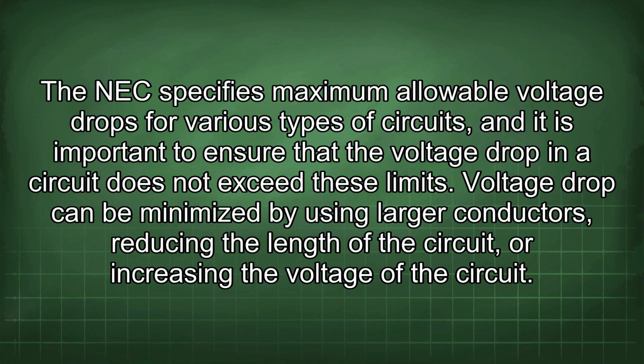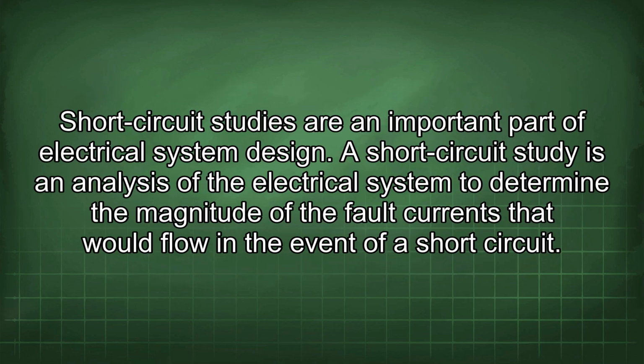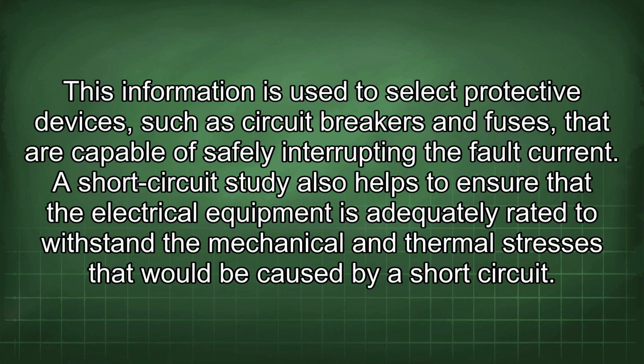Short circuit studies are an important part of electrical system design. A short circuit study is an analysis of the electrical system to determine the magnitude of the fault currents that would flow in the event of a short circuit. This information is used to select protective devices, such as circuit breakers and fuses, that are capable of safely interrupting the fault current. A short circuit study also helps to ensure that the electrical equipment is adequately rated to withstand the mechanical and thermal stresses that would be caused by a short circuit.